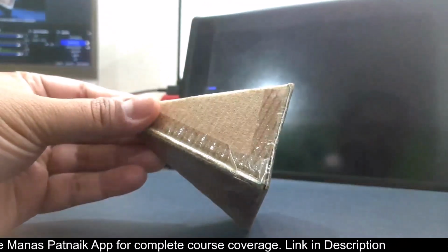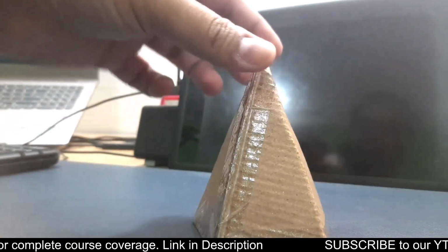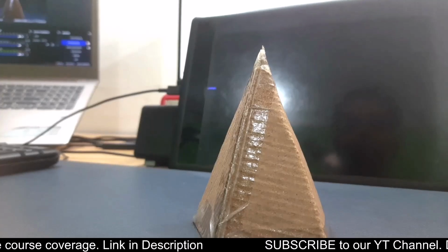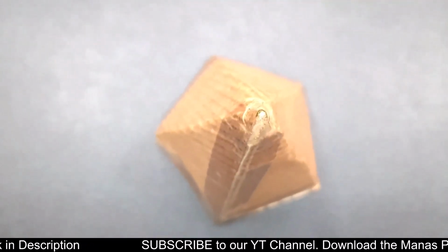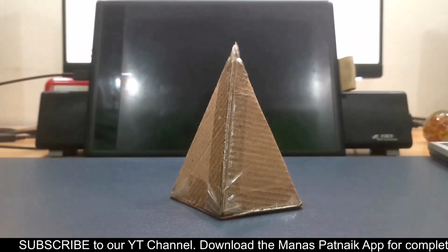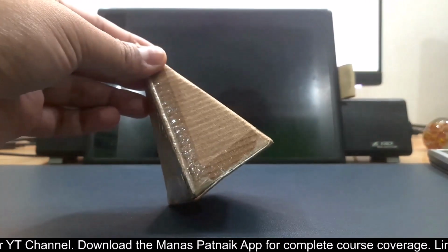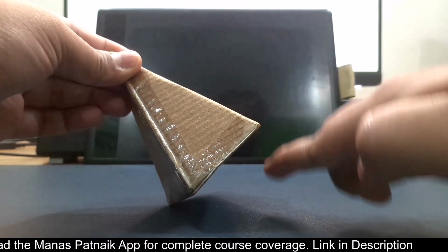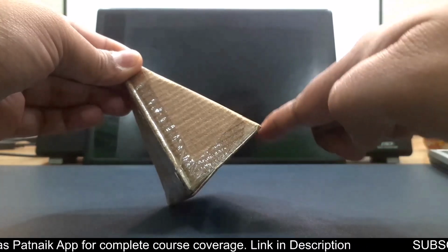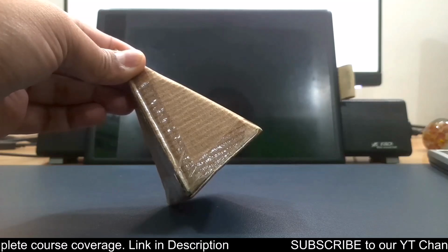So take a look now. We are not exactly in the front view. I have shifted it. So step number 1, we are going to simply keep it like this. We are going to start by creating the top view first. Okay, and then the front view in this fashion. I hope you are getting this right. In step number 2, we'll do it like this. We are going to recreate the front view from step 1 into step 2 using this height of 45 millimeters, this edge over here, which remains parallel to HP. In step number 3, it has been clearly said in the question that apex is nearer to the VP.